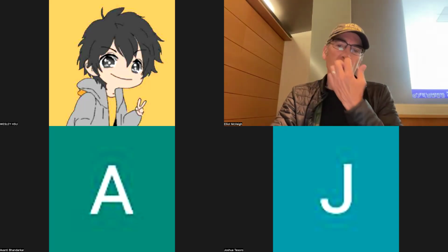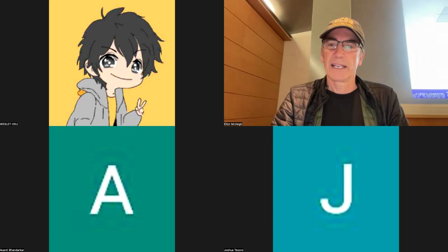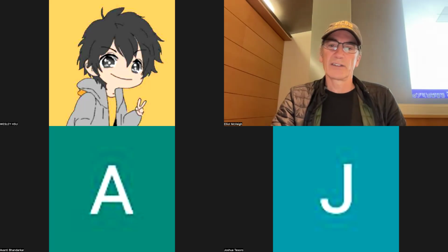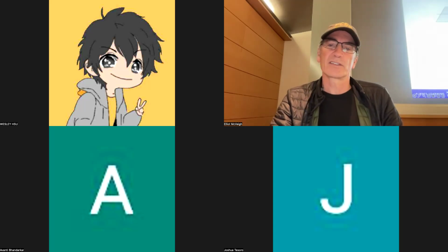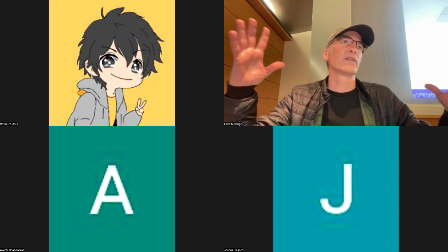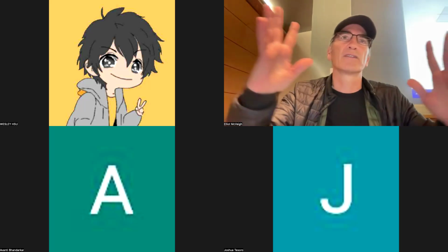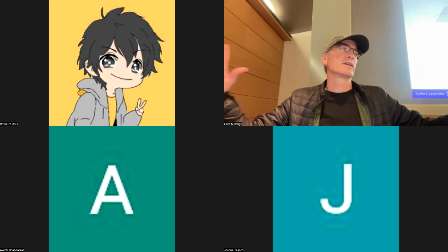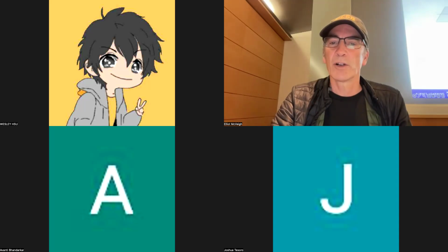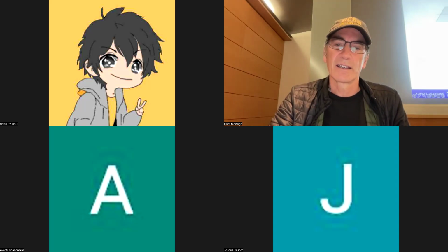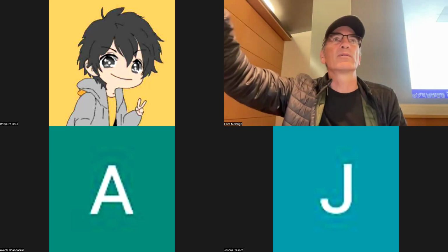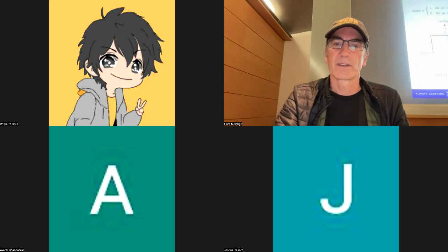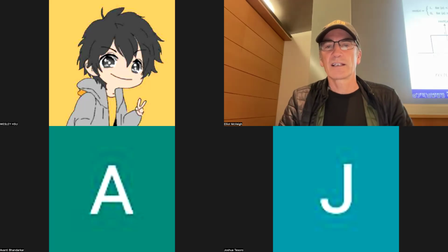And here's what you could call a sample comb. I have a whole set of delta functions, evenly spaced on the 2D plane, and the distance between the delta functions is given by delta x and delta y. I can make these independent, but if I make the two distances the same, like that comb function or sampling function, I can make it a very dense sampling or a very loose sampling by changing that. So now if I multiply a function times this, it's going to sample that function at very discrete points.